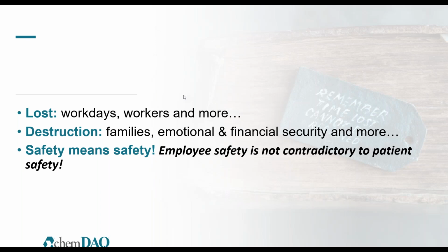Yeah, one thing that we found when we first introduced our peracetic acid monitor, at the time, this was before the ACGIH TLV for PAA, and so a lot of places like aseptic filling lines, they were only monitoring for hydrogen peroxide and acetic acid, and there were at least a couple of plants where their workers were complaining about sore eyes, nosebleeds, and other signs of irritation, but the hydrogen peroxide and acetic acid levels, when they were checked, they were fine.